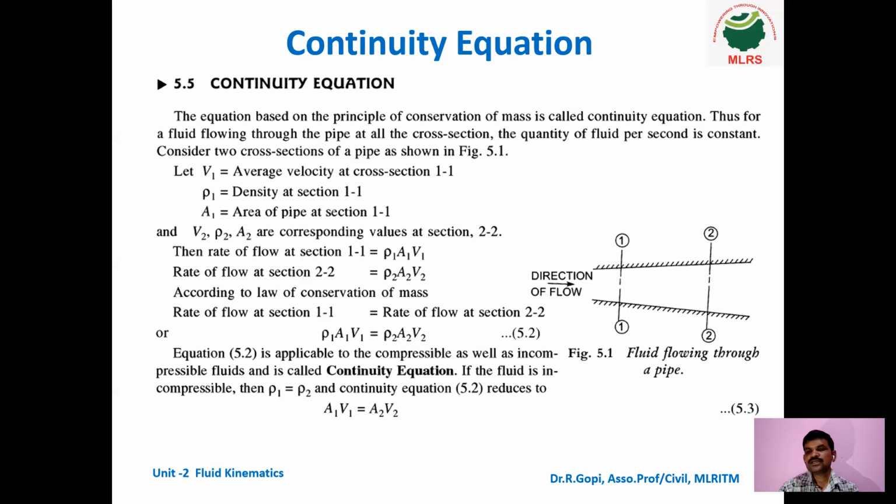Discharge is the same. In unit 1, we saw Pascal's law, so pressure is constant in any direction as per that law. Similarly, here the discharge is constant. Even though area and velocity are different, whether it is a uniform pipe, a tapered pipe or a non-uniform pipe, discharge will not vary. You can check anywhere, discharge is constant.